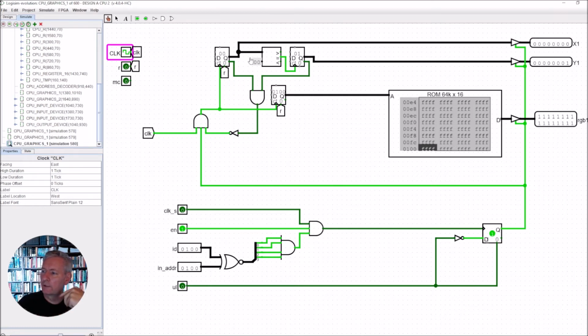Now this will continue doing this until we get the overflow coming out on this line here. That means that the X has counted to 256, and the overflow will come out in this Y counter here as well at the same time. So this will have counted 256 X, and this will have counted 256 Y. The two values here will go high, so this will go high here, and this point here will now go low.